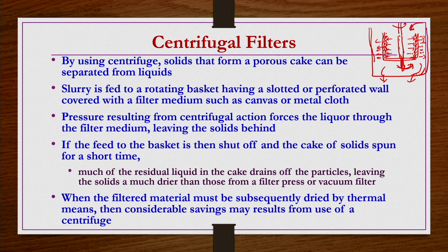Now, further, sometimes you need to dry the solids. Let us say you have taken the feed slurry and separated the solids and the liquid into phases by applying the centrifugal force in the centrifugal bowls, right. Now, obviously the cake that is deposited on the surface has a wet nature, because the interstitial spaces between the solid particles are in general occupied by the liquid, right.